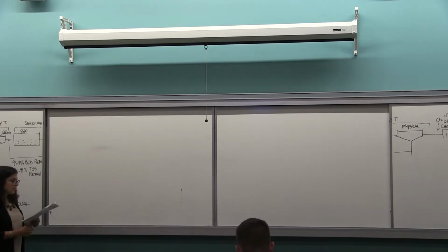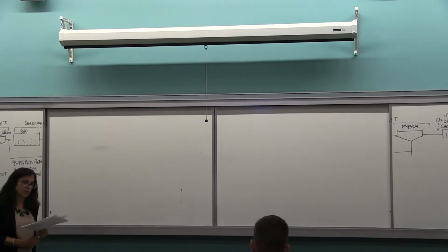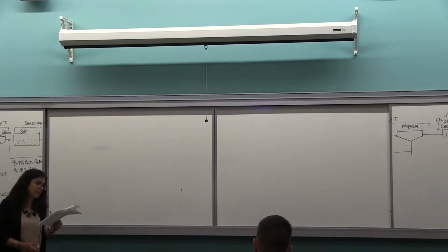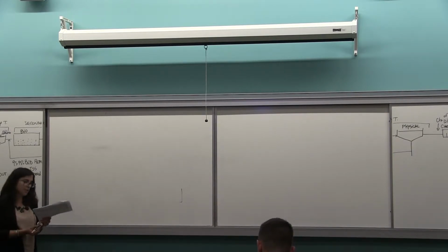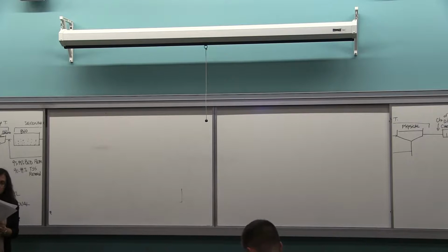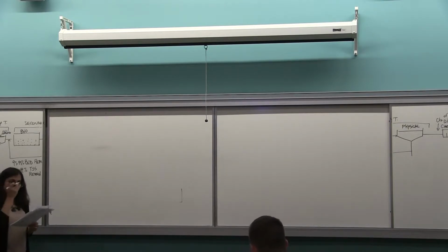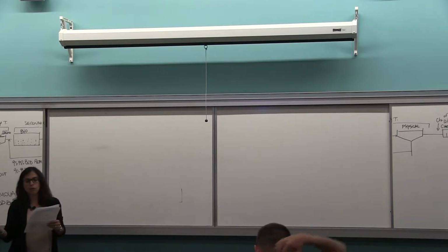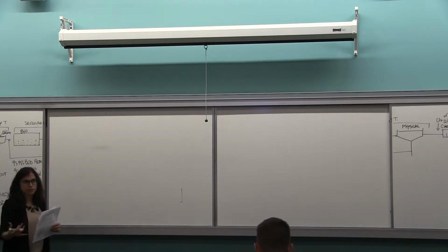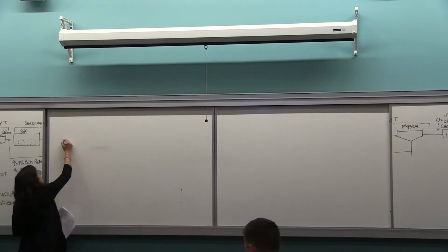So the first problem is: we have a community with a population of 25,000 planning to expand its wastewater treatment plant. Using the table below for daily flow and assuming a 15% population increase over 5 years, and the peak factor being 2.5, what is most likely the peak flow at the end of the 5 years time? All right, so